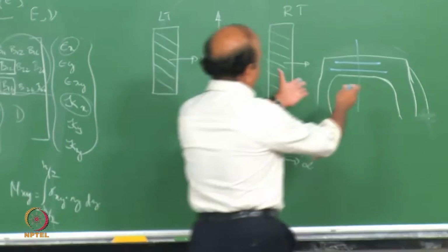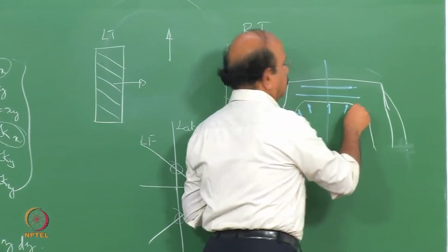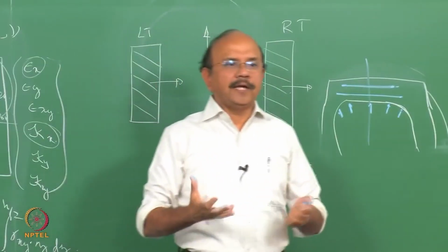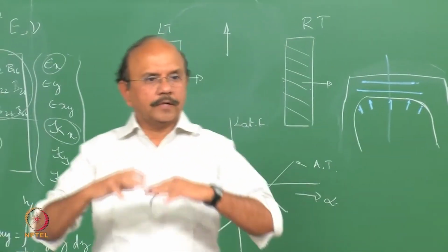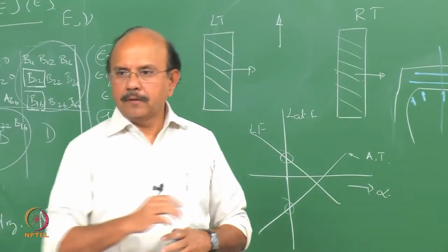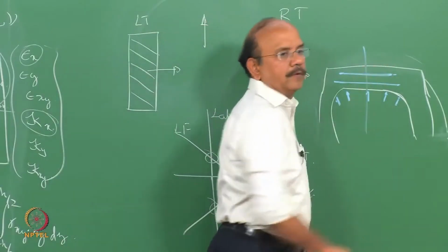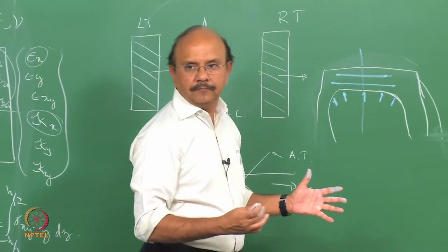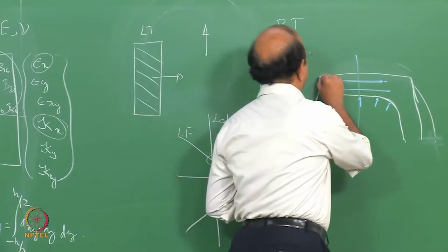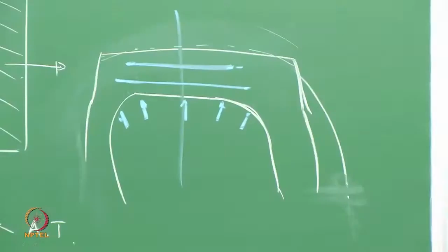There is a stiffness that's given to the tire because of these belts. So it assumes a uniform radius, or in other words, the deformations on either side are the same. Right? Let's say that's the deformation due to inflation of the belt. Inflation with the presence of symmetric belts.